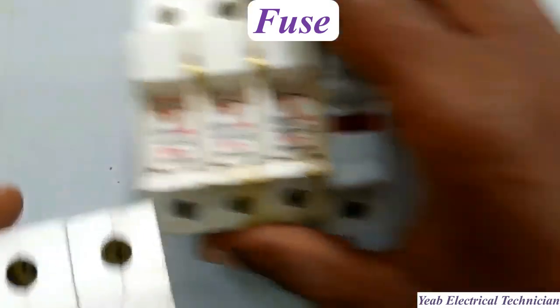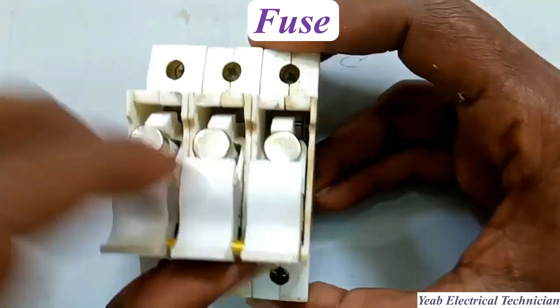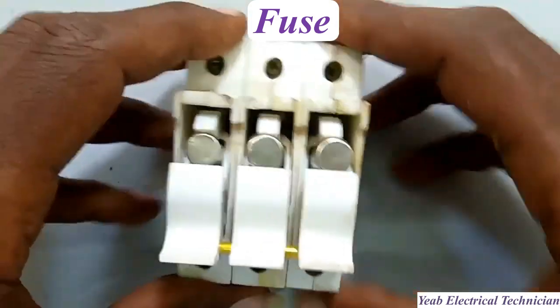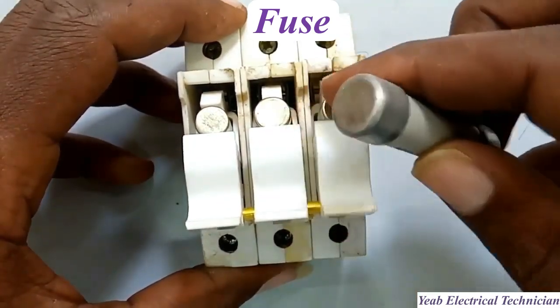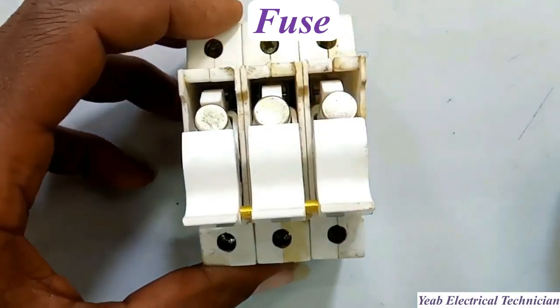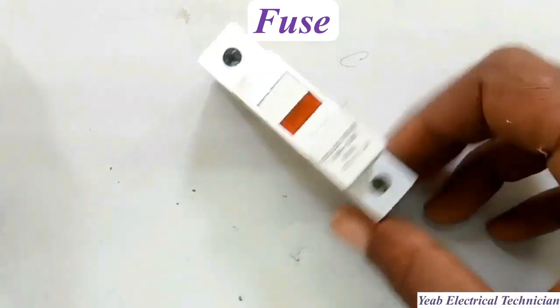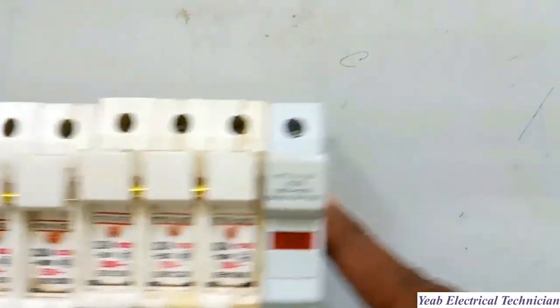Under normal conditions, the fuse allows electrical current to flow through it without issue. If a fault like a short circuit or overload occurs, the current increases dramatically. The excess current generates heat, which causes the fuse's internal wire to heat up until it melts. The melted wire breaks the circuit, stopping the flow of electricity to the device or wiring it protects.